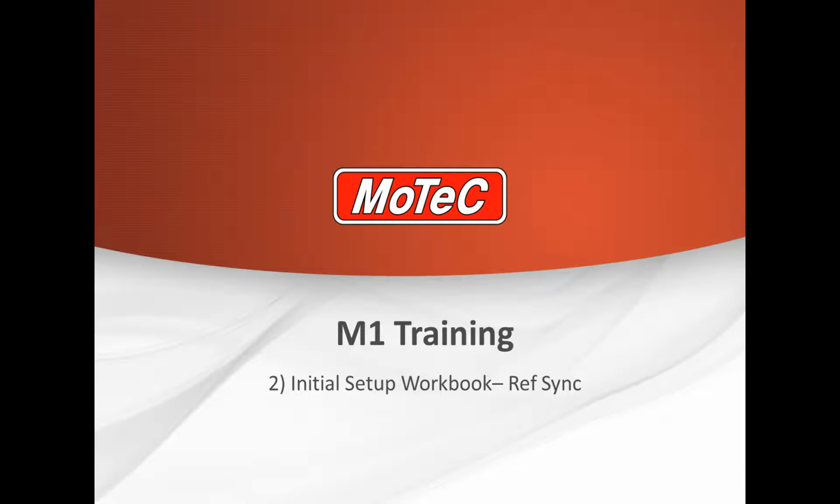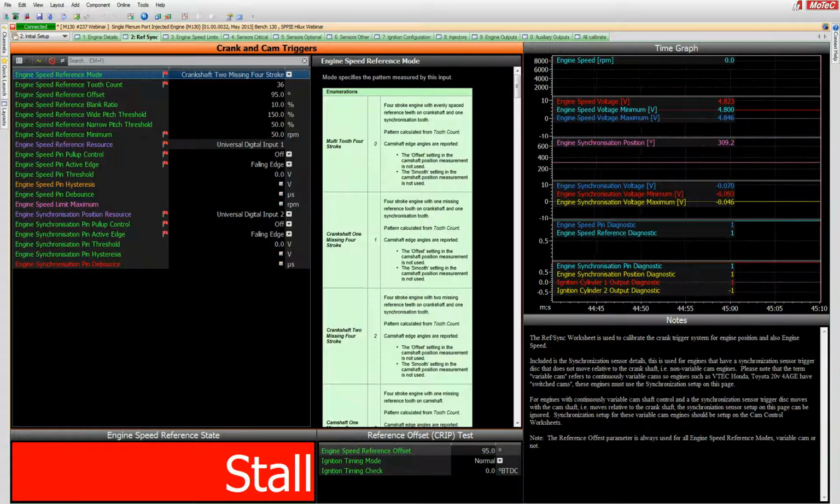So if I move over to my M1 Tune software, I'm already online with this ECU. I assume you would have seen how to do that in our other webinars. We can see over on the right I've got some scrolling parameters. This is like a time graph based on the actual information coming into the ECU at the time. So I'm on my initial setup workbook and I'm on worksheet number 2, which is ref and sync.